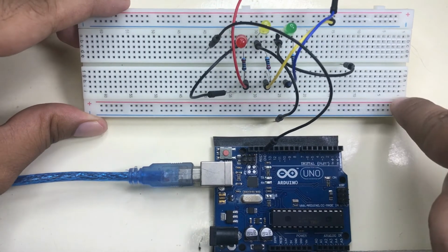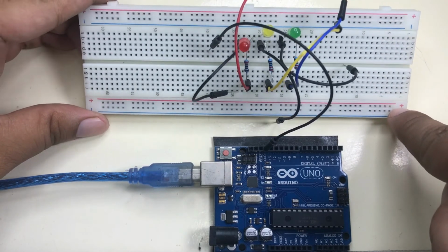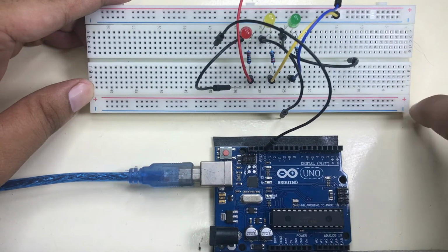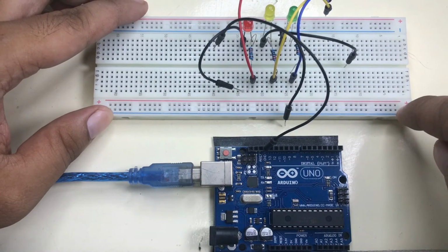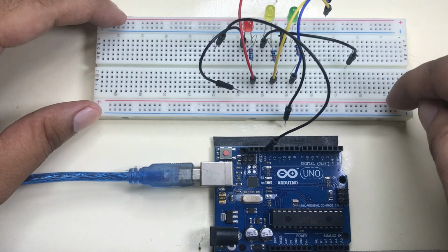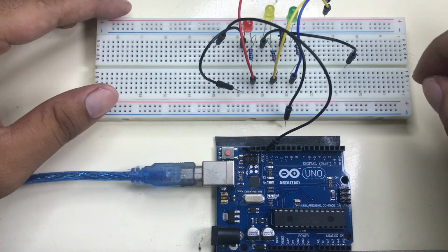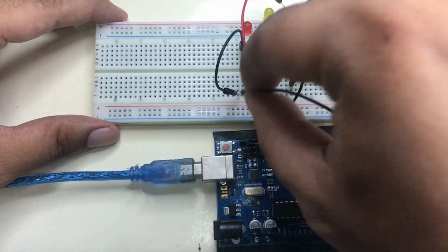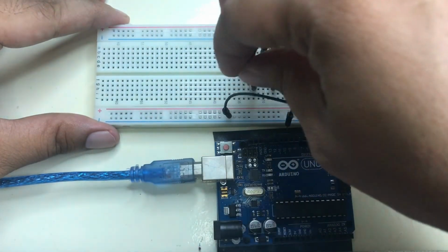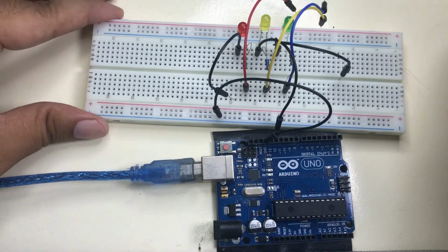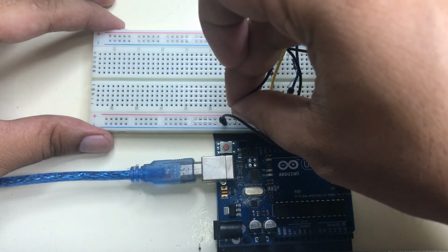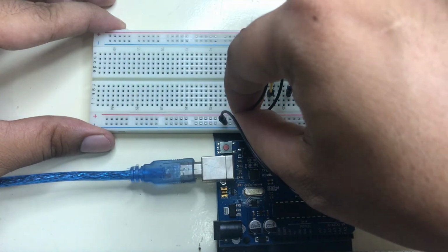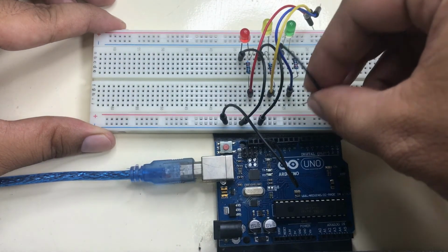We can use these straight lines, the horizontal line, because from point here to point on this side, it is connected. So wherever we connect the black wires on this part will be also connected to each other. Since we have here the negative sign, we will use this negative sign, so we have to choose the blue one. So all black wires or the ground wires should be in line with the blue line. Okay, and black.